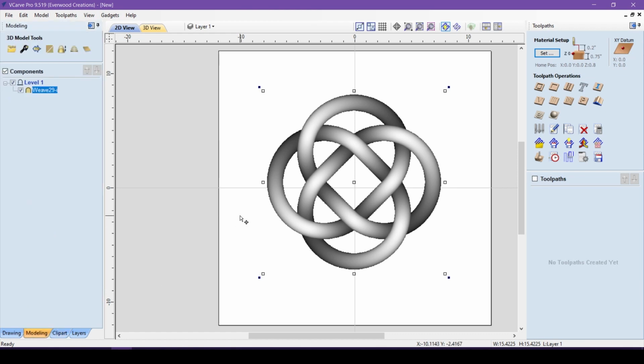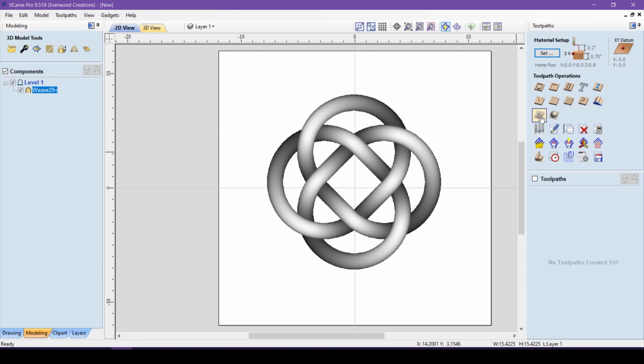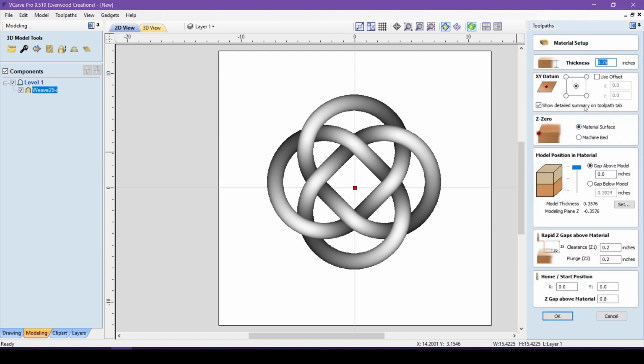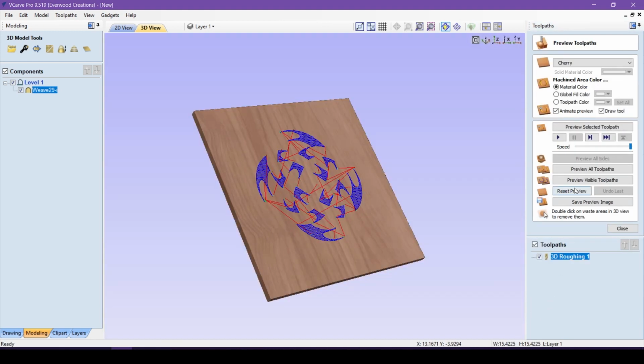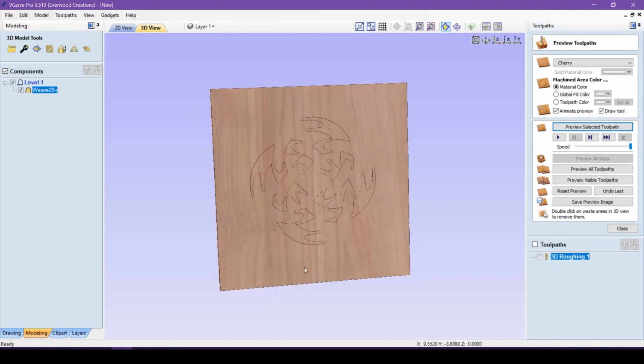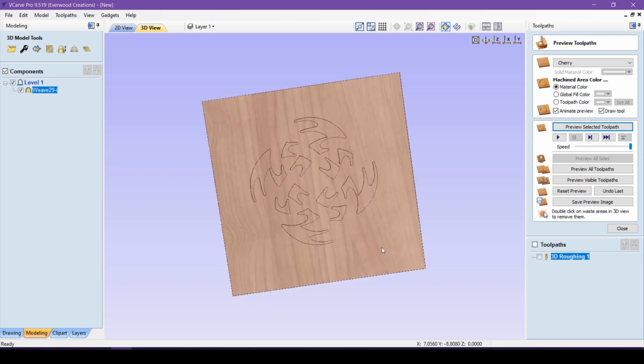Finally, we have the 2 actual 3D toolpath options. The 3D rough toolpath allows you to use a larger tool to clear big areas from a 3D carve, reducing both time and wear on tools for the 3D carving process. This path clears the way for the more detailed work of the regular 3D toolpath.